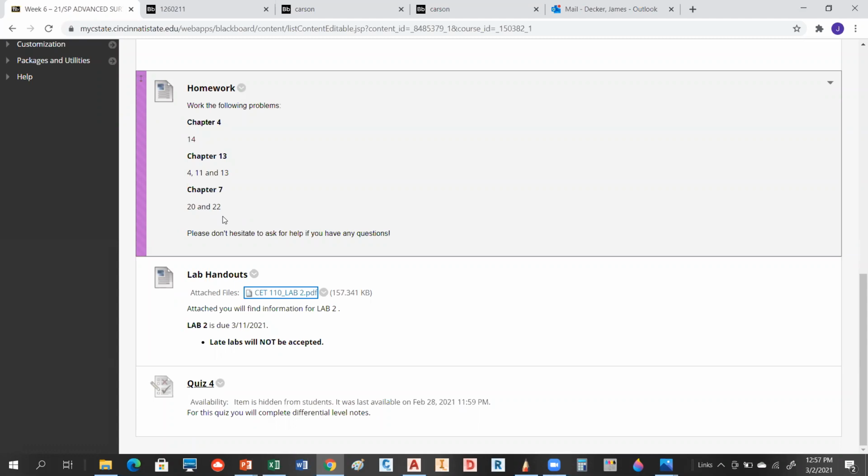So the tape is calibrated at 100. And it's actually found to be 100.01 feet. That's its true length. What's happening there? That's an instrumental error. It is, and it would be called an incorrect length of tape error. And would this be systematic or would this be random?